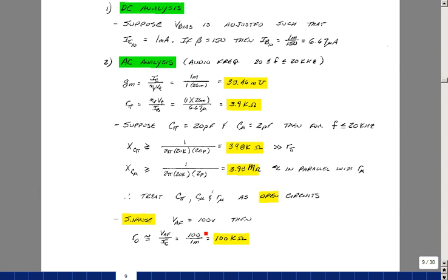Now an early voltage for our transistor would be somewhere in the range of 100 volts or so. And so just using the approximation formula earlier in this lab lecture, 100 volts divided by the biasing of 1 milliamp would give us about 100K.